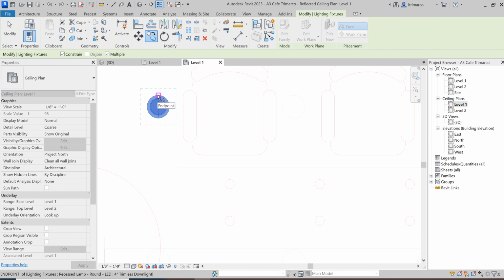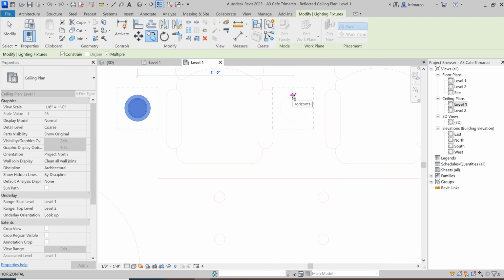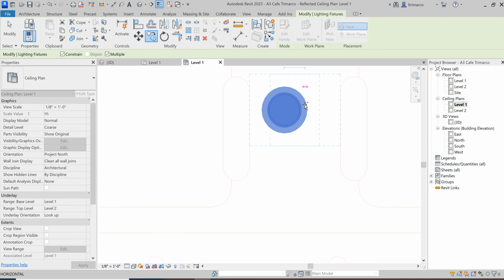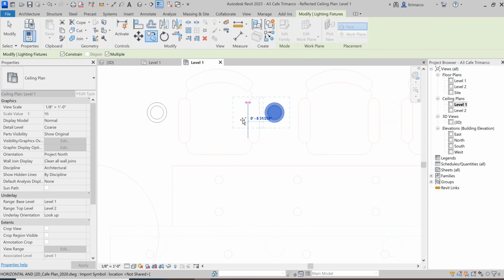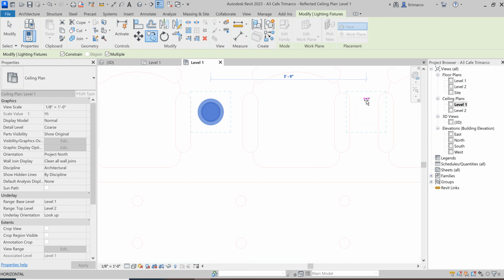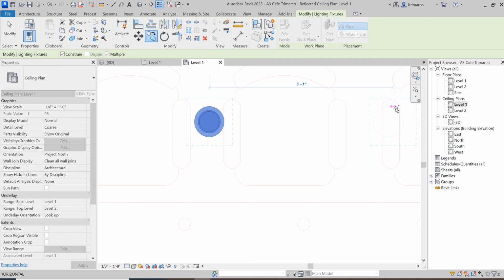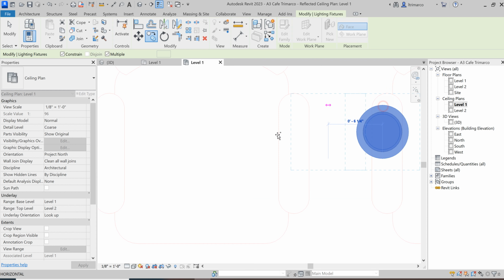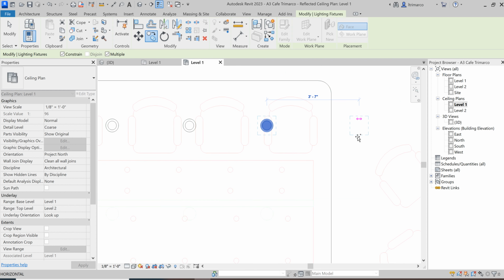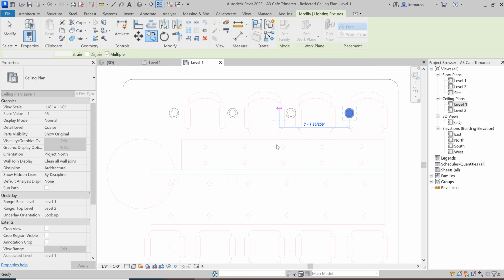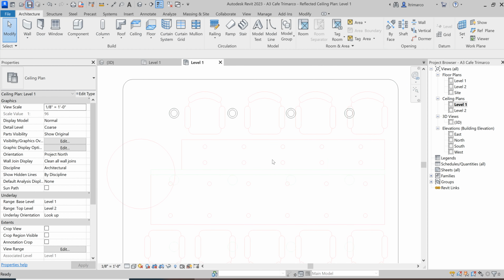So on the actual selecting of the original object to copy, I'm able to select endpoint here. But as I move to the next option, I get only a double arrow and it says horizontal. And all I can say is that is a good thing. It's just difficult not to see endpoint to endpoint to endpoint because that's what we're used to working with in AutoCAD. But if you scroll in, it knows to snap at the midpoint of the AutoCAD circles.